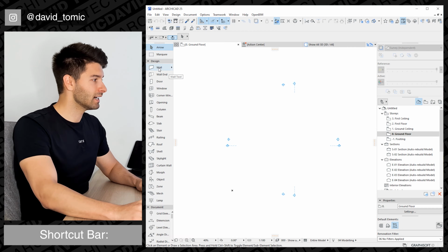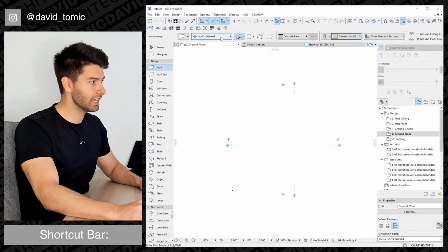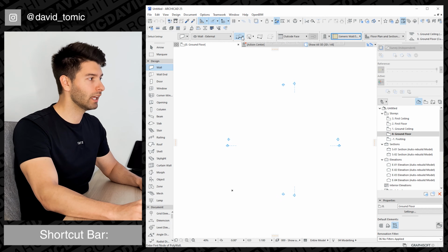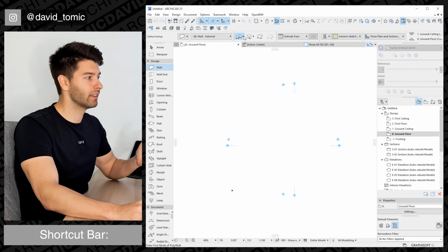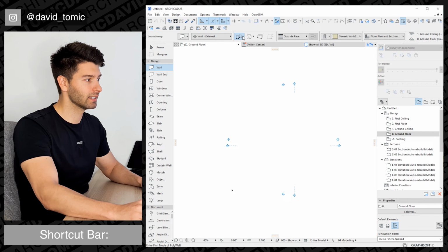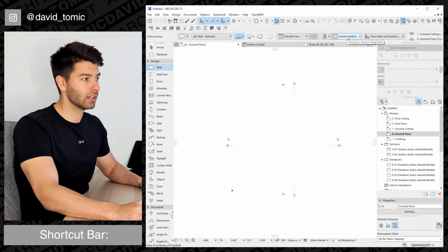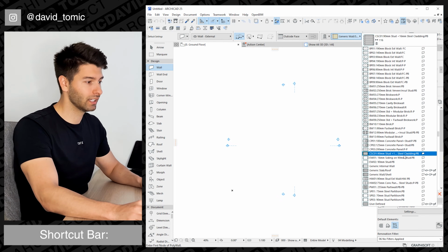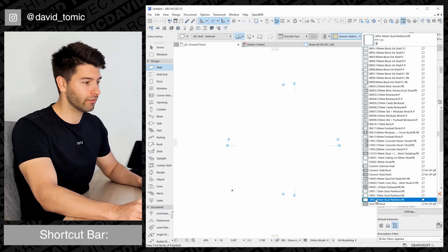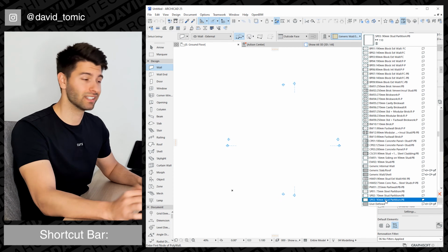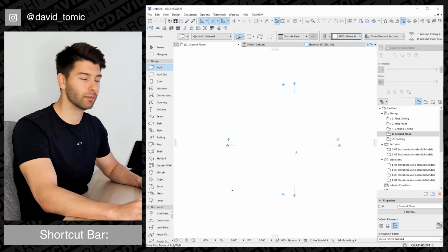I'm going to make it relatively nice, but we're not going to spend all day on internal fit outs, room layouts, and all that. Let's start by selecting our wall tool. Next, we want to make sure we're on our wall external layer. We have our geometric method shaped continuous line selected. If you don't, press and hold, and you can change what sort of shapes you're using and need. Next, I'm going to come across to my wall structure, click all the way down, and find my stud partition. I'm going to make this a timber frame house, so 90mm stud partition's perfect.